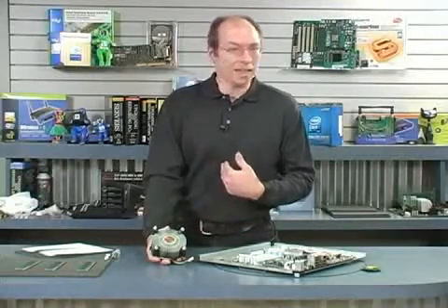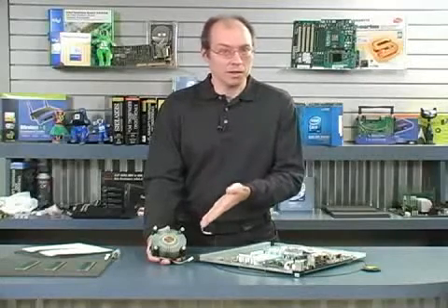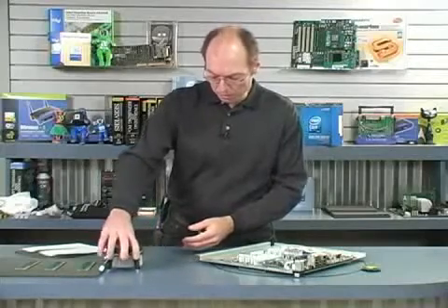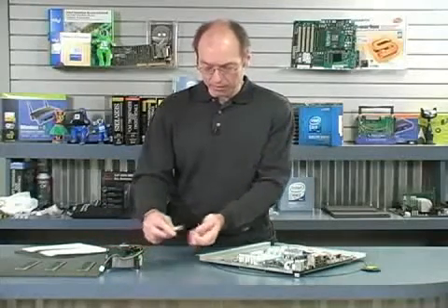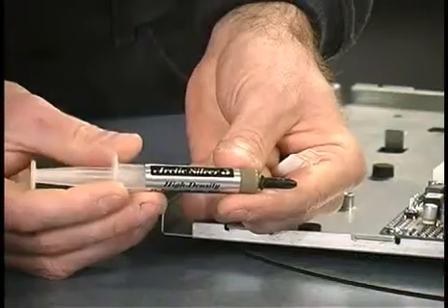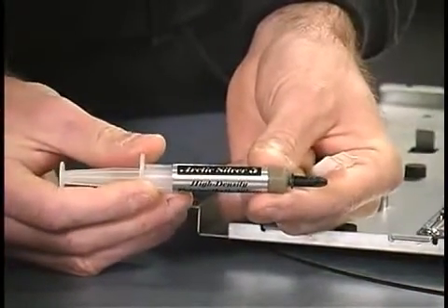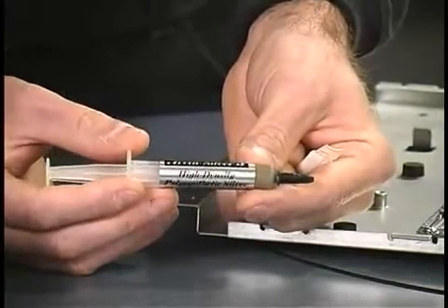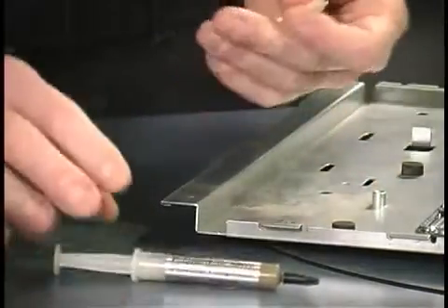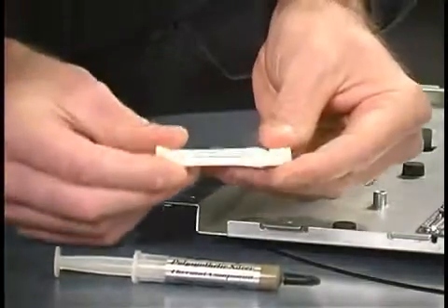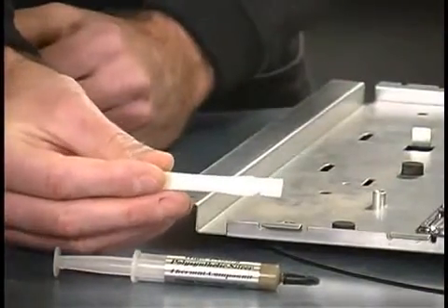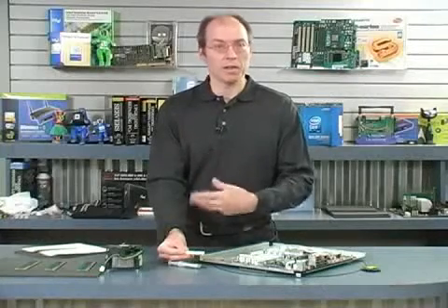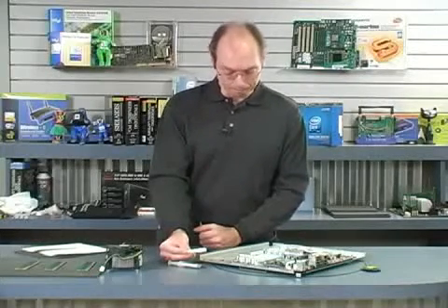And since, as an individual, I can't really get the phase change stuff, because the only way you get that is pre-applied, we have to use what's called a thermal grease. Thermal grease usually comes in packages like this. Here's a package of what's called Arctic Silver, and this is enough for probably hundreds of applications. There's enough in here to install 100 heatsinks on 100 processors. Sometimes when you buy a heatsink, it will include a small amount of thermal interface material like this, which is good for maybe 1 or 2 applications. They just give you enough that you can get it properly installed at least one time.